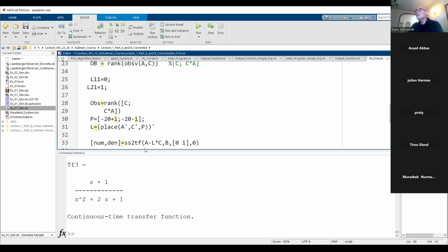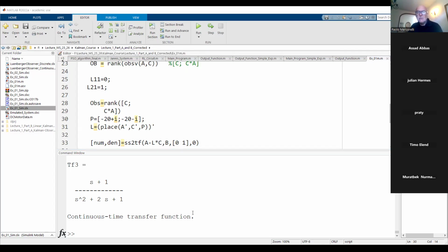Let me run now. But now, do you remember the concept of placing arbitrarily the eigenvalues? Faster and faster dynamics means larger and larger eigenvalues in absolute value. Now, the eigenvalue is less in absolute value. Instead of 220, I'm waiting for slow observation. This means the dynamics of the error will be slow. I will converge slowly, but probably I will have a peaking phenomenon a little bit less. Let me show you. Significantly less, I would like to say, because I reduced 10 times. No?